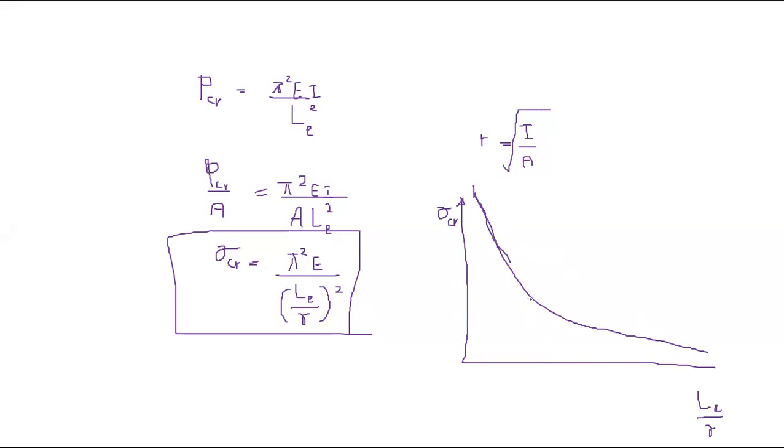But can you have infinite buckling? No. There's another criterion which governs the failure there. What's that? Yielding, right? So the material crushes. The material has some compressive strength, right? Compression yielding, so it will fail by compression.